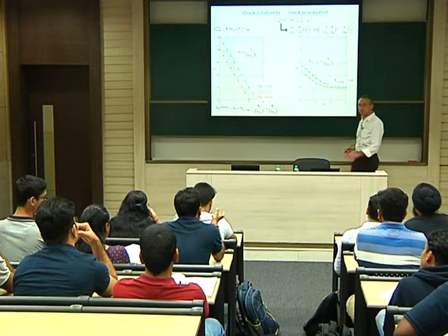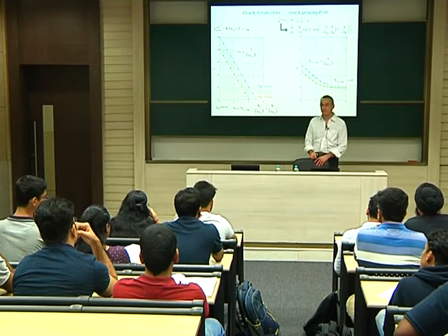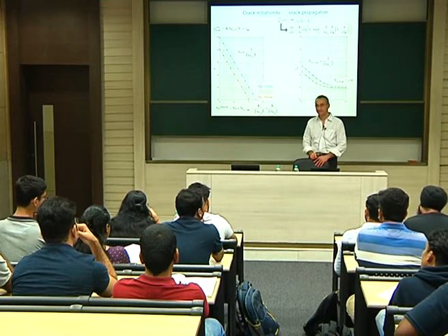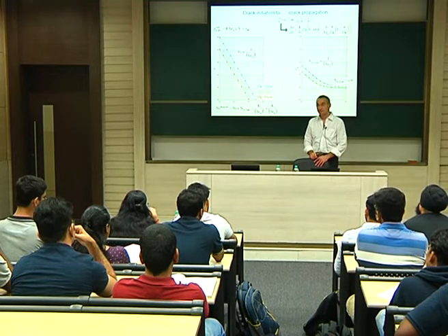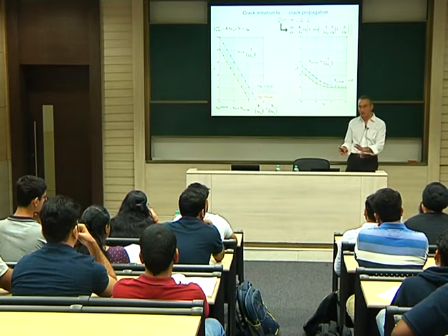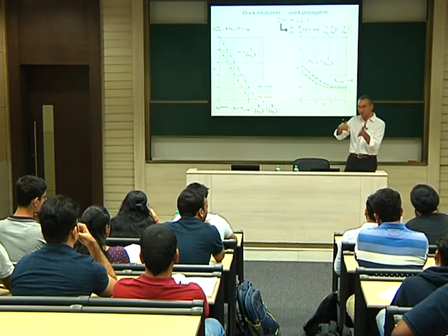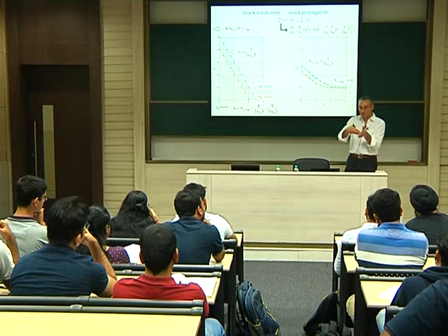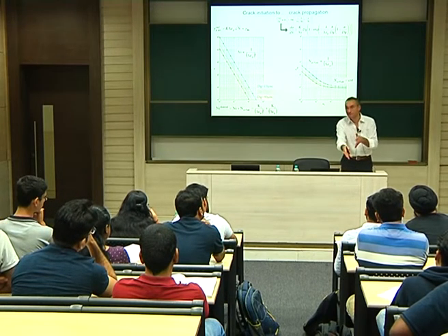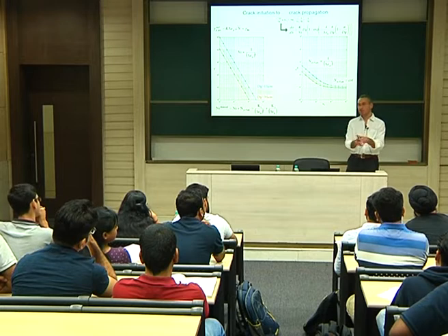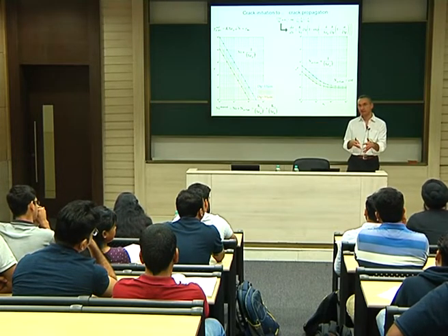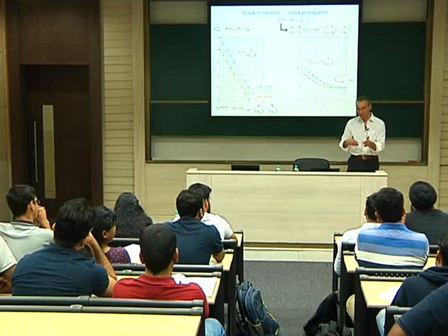Yes, we assume. Yes, that's true. I don't know. It's just because the slip dispersion is less. So this is just our conclusion. Just because when your crack is close to a small grain boundary, then the slip dispersion remains more or less confined, so the crack will still advance. In the big grain, the slip dispersion will occur very heavily. This will slow down your crack. So your crack will slow down in big grains. In small grains, it will not.